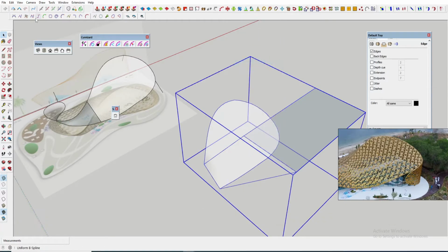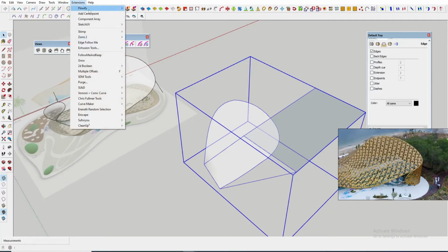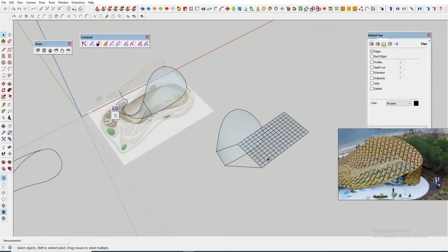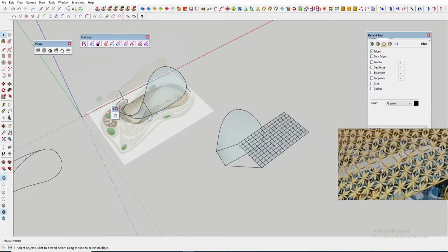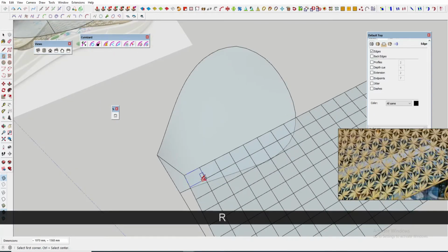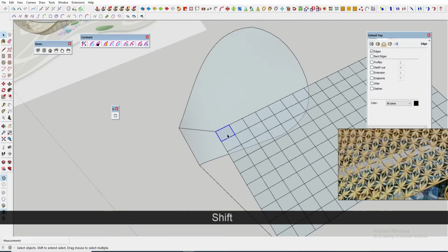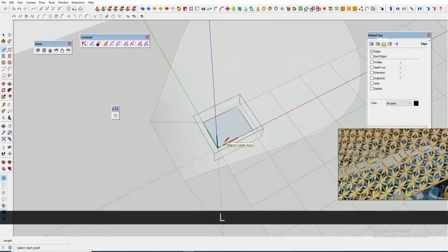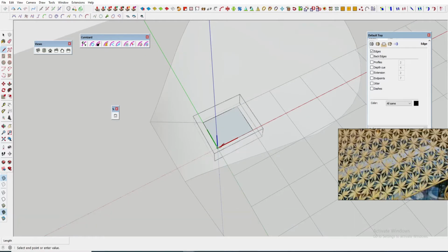Afterwards, we need to use Flowify impose grid, so we'll get all the quad faces on the projection plane. Now above the projection plane we can add that geometry, meaning the pattern. Here I am following the same pattern. I am making each quad face a separate component, so we can adjust easily.